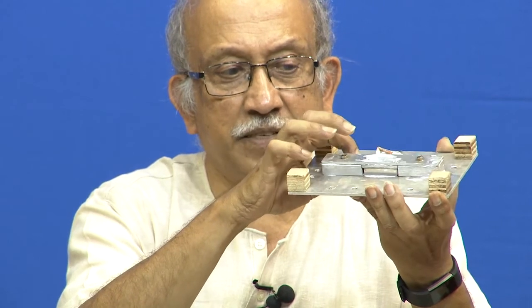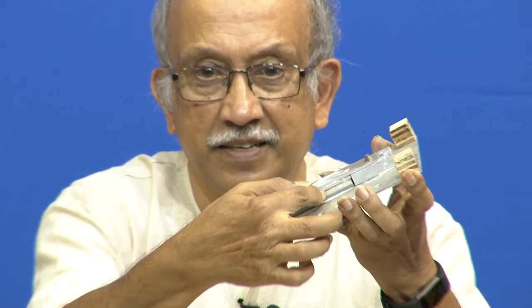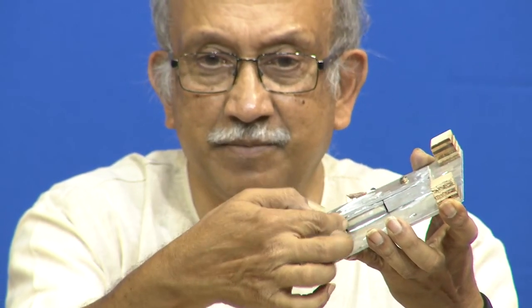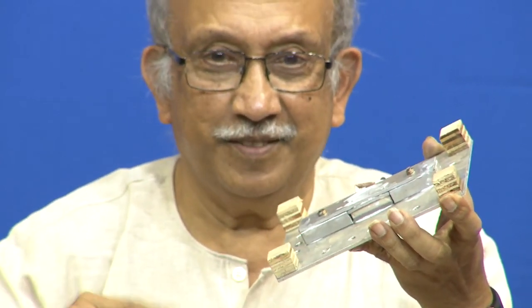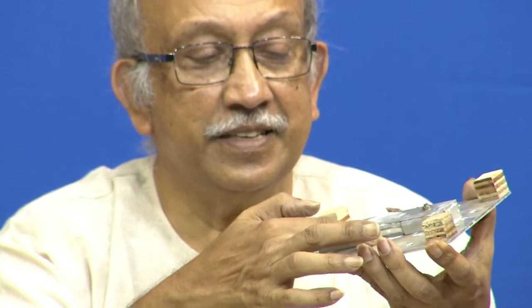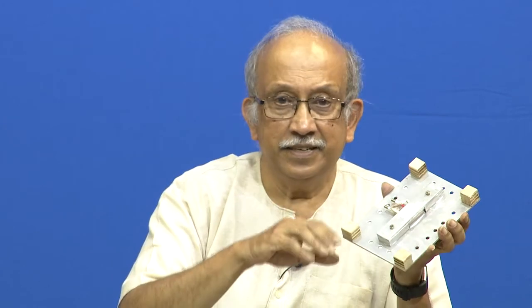I have clamped something on top, something at the bottom, and then you can see here there is a small ceramic thing. It is actually nothing but a thermistor with two slopes of positive temperature coefficient, like this. With this, it has a self-regulating property. As things heat up, it will allow a large current to flow. When the temperature is below a certain set temperature limit, it allows a large current to flow. Once the temperature has reached maybe 60 or 70 degrees, it will reduce the heat flow and maintain it at that.